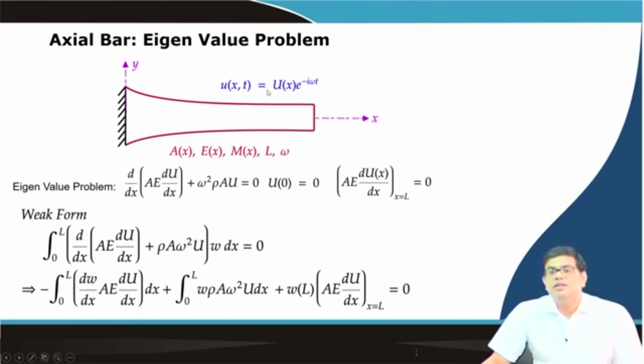With the separation of variables, the time solution and space solution are separated out. Now in case of a simple bar problem, this quantity is 0 because there is no force, because it's a free vibration problem. But a free vibration problem needs an initial disturbance to start.